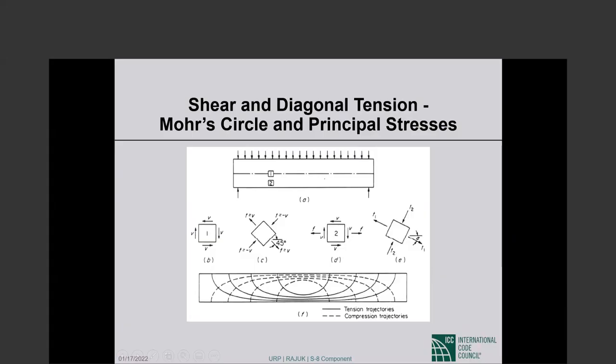Okay, these tensile stresses, quite often, actually, unless you are here someplace, these stresses are inclined. These are inclined tensile stresses, not parallel to the neutral axis as we typically visualize. And these inclined tensile stresses will cause cracks perpendicular to the tension. So unless we have reinforcement trying to minimize those cracks or contain those cracks, we will be in trouble.